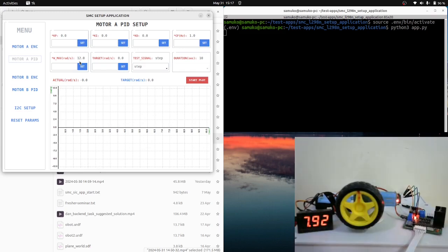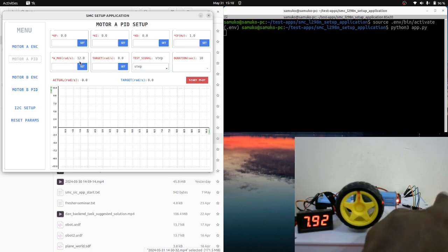Because the module is doing things like filtering, also doing PID operation, and also reading bipolar pulses using interrupts. So it needs to note how it's doing all these operations. Now, the way the module calculates its pulses per encoder, its velocity, is using the time difference between two pulses. Because of that, it's not very good for high frequency applications. So there's a need for that limit so it doesn't affect the process on the microcontroller.